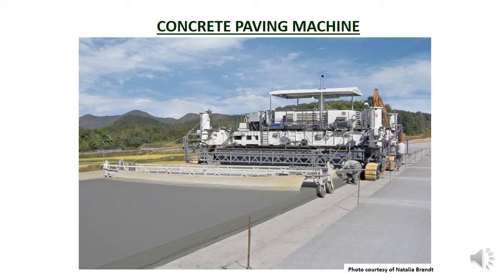In this case the road does not seem to have any reinforcing, and this is common with concrete roads, as the main stresses on the slab are compressive, which can be taken by concrete alone if the road is thick enough. However, there needs to be an allowance for expansion of the concrete, and expansion joints may be cut into the concrete after it is set.